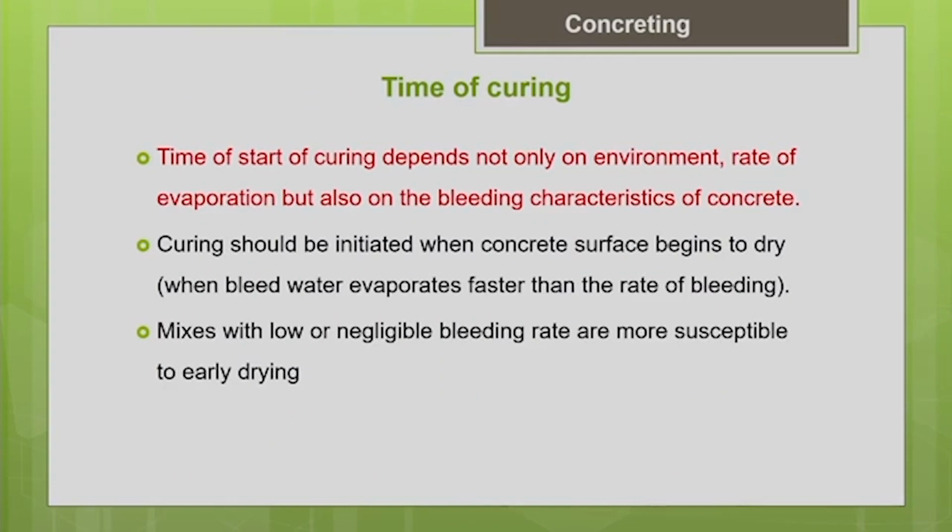Generally we cannot generalize when the curing has to be started for a concrete. What should be the right time of curing varies from concrete to concrete, and from environment to environment where the concrete is being done. In aggressive environment conditions where the rate of evaporation is very high due to high wind velocity or high temperature, we have to start the curing as early as possible.